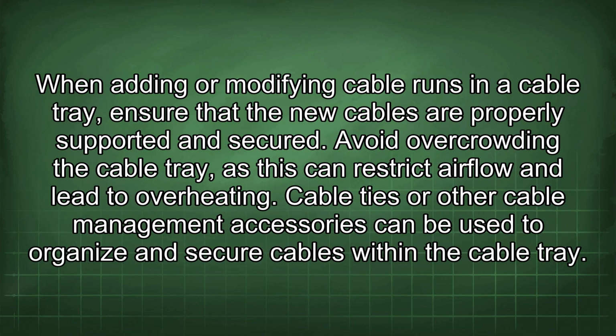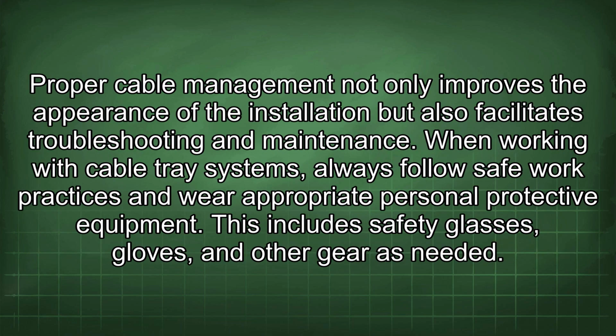When adding or modifying cable runs in a cable tray, ensure that the new cables are properly supported and secured. Avoid overcrowding the cable tray, as this can restrict airflow and lead to overheating. Cable ties or other cable management accessories can be used to organize and secure cables within the cable tray. Proper cable management not only improves the appearance of the installation, but also facilitates troubleshooting and maintenance.